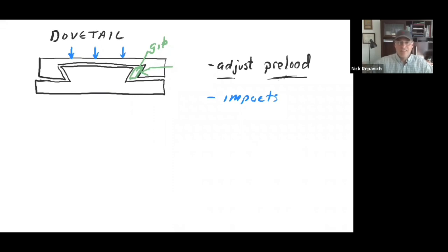Instead of being straight, they'd be S-ing through the field, because the aluminum expands so much that the only way is if it was no longer straight. It was a big curve. I mean, we're talking 20, 30 foot deviations out through the field with this aluminum structure. And it just jumps out. It's like, wow, that really has a coefficient of thermal expansion, doesn't it?